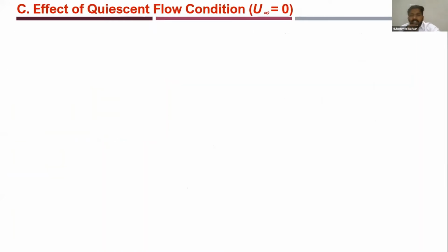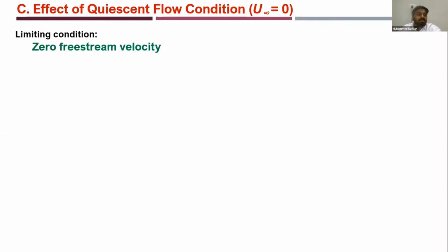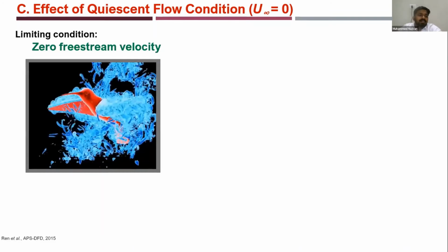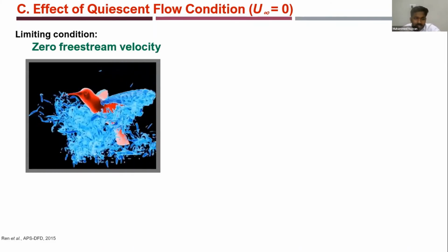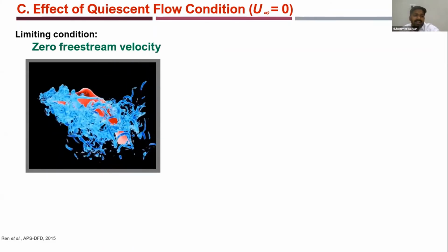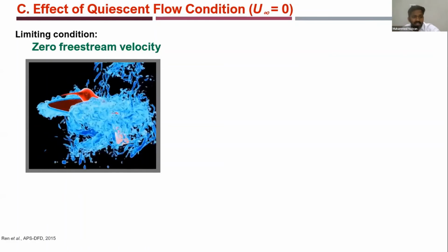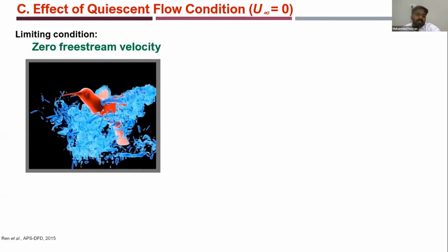So till now, we have seen how the vortices change in the presence of free stream, from a drag producing to a thrust producing or a deflected wake as we increase the Strouhal number. It would be really interesting to know the limiting case when the Strouhal number is infinite, or at zero free stream velocity. A similar phenomenon is observed in the hovering of a hummingbird, where we can say that it stays afloat in a single position without moving by just flapping its wings.